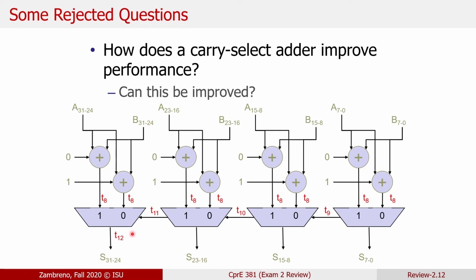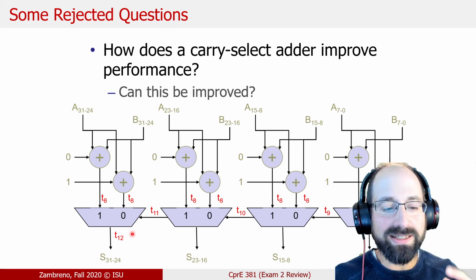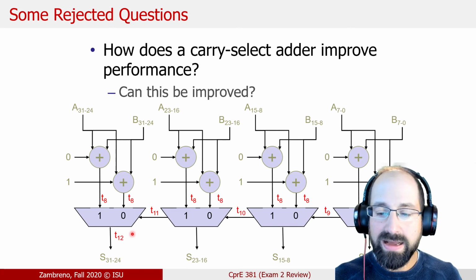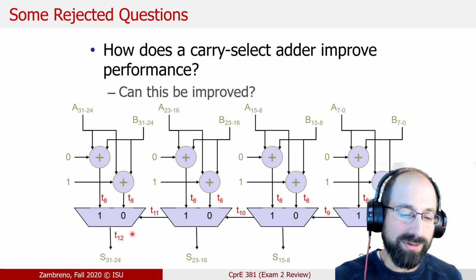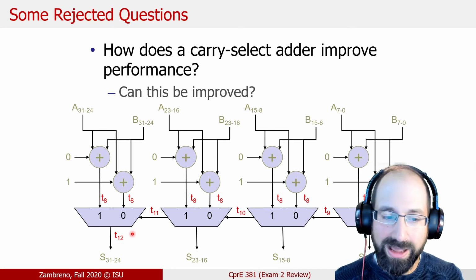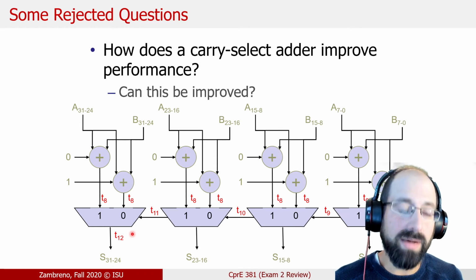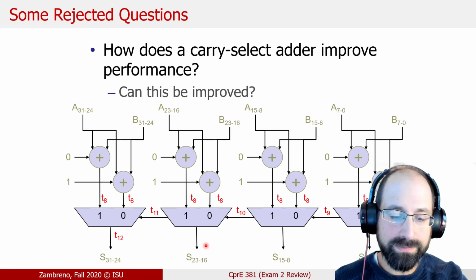Adder design and multiplier design is still kind of an open area of study and evolution. Our goal is to have an ALU that you can debug in a feasible amount of time in the lab, right? But you can make your adder significantly faster. There are always a couple of groups each semester whose goal is to maximize the clock frequency of your pipeline or single cycle MIPS processor. The adder will be part of that critical path, and so these are the kind of things that you can explore. I'm happy to help you explore as well: minimizing your critical path, but maximizing your clock frequency.